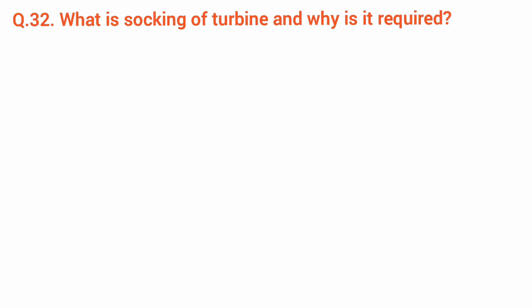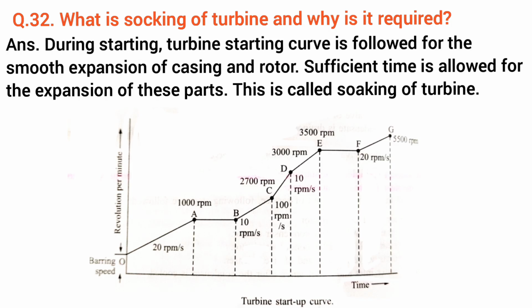What is soaking of turbine and why is it required? During starting, the turbine starting curve is followed for the smooth expansion of casing and rotor. Sufficient time is allowed for the expansion of these parts. This is called soaking of turbine.